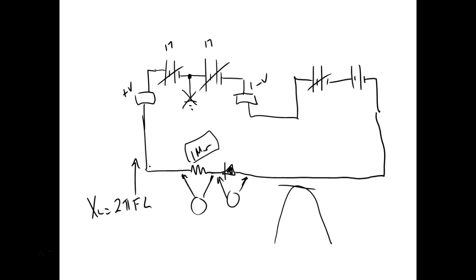So this is what we'll do, we'll break it over as a class, because I don't want y'all dealing with it. In this class, we don't want to deal with any high voltage. Let's save that for motor controls. But here, we don't require y'all to wear the PPE, right? Even though I should be wearing some. I'm the instructor, I can break the rules, right? But y'all would have to put on your safety glasses, you'd have to have gloves on and all kinds of stuff, anything above 50 volts.